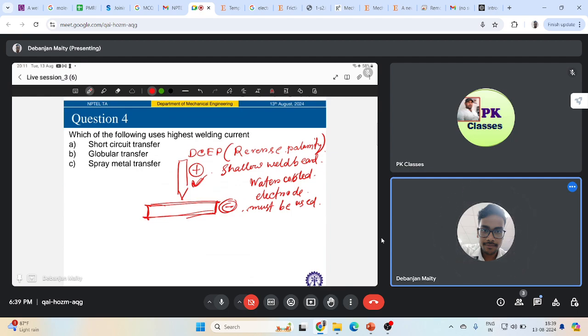Right? Now, what electrodes can we use? In general, with tungsten electrode, we mix up cerium or thorium, right, to have better electron emissivity, better current carrying capacity, or resistance to contamination than pure tungsten electrodes. So as a result, if you are mixing these materials with pure tungsten, the starting of the arc will be much easier. The arc will be more stable, right?